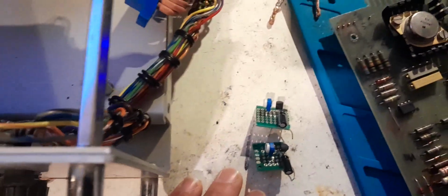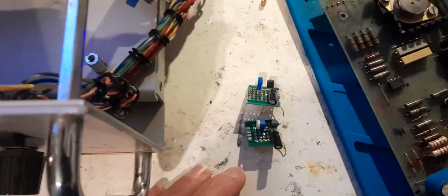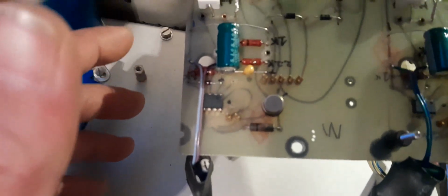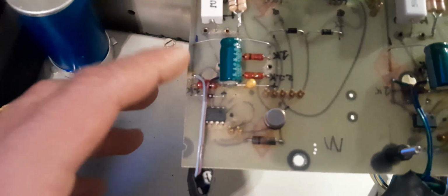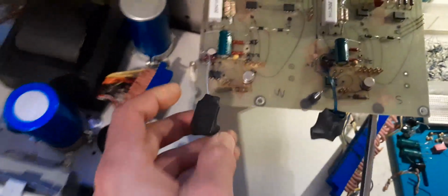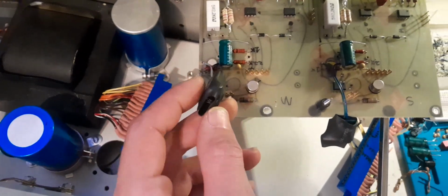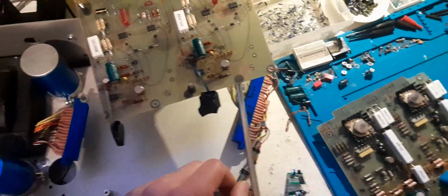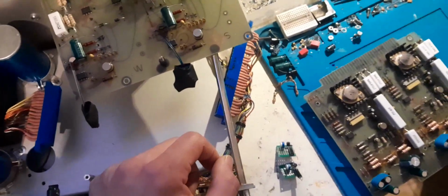So before I come back and make more video, I think I'm going to convert these two to ATL431s, and I'm going to keep these ones as TL431s because, for high current, they're alright, but I'm going to put them on the board, and I'm also going to put 47 microfarad caps with 1 microfarad MKTs on them. These already have the MKTs on the back of them, but they've only got the 4.7 microfarad cap inside there. So that's my plan. And then we'll come back and have a quick look at what's going on.